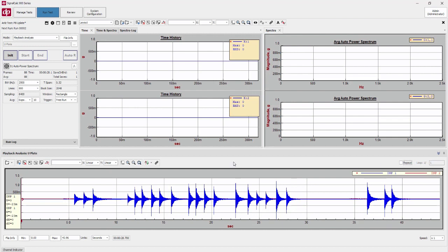Or in other cases, instead of playing back the complete data, I want to focus on the segment of interest. For example, if I want to just analyze the data between these two cursors, I'll place my double cursors and click on the min and the max, which would lock the cursor locations, the first cursor and the second cursor.